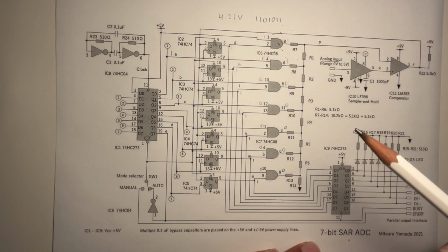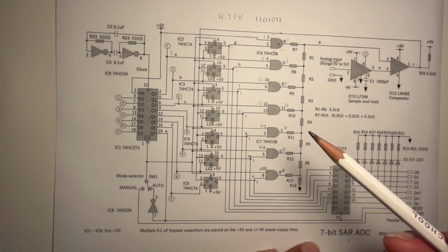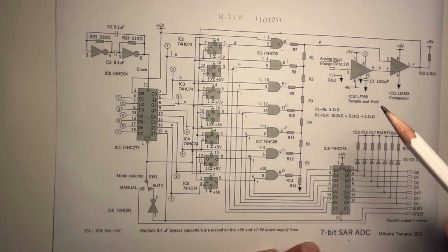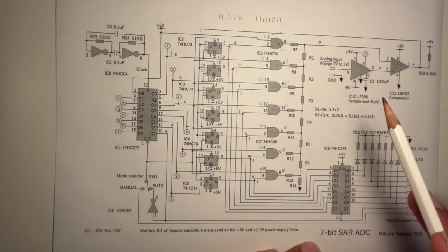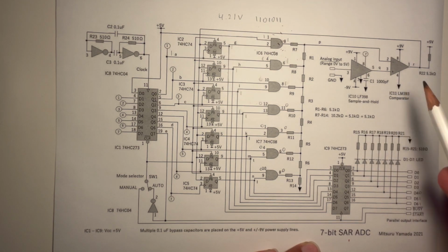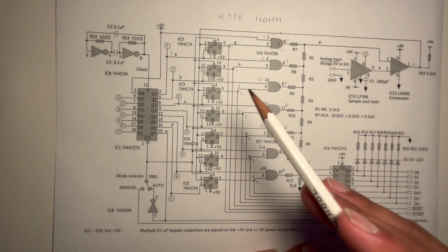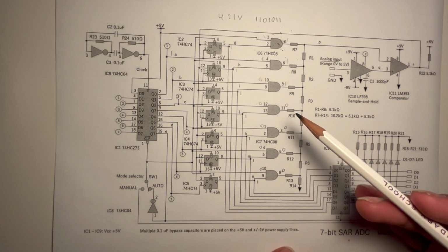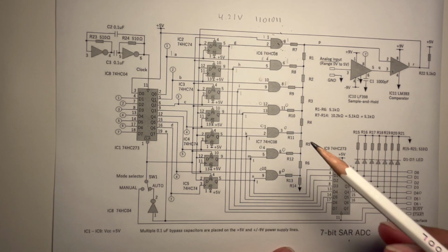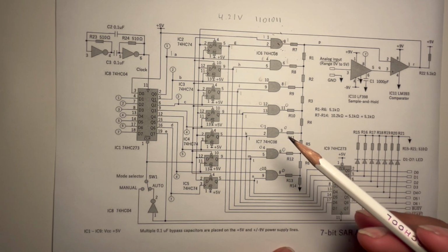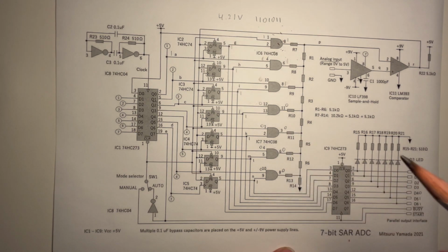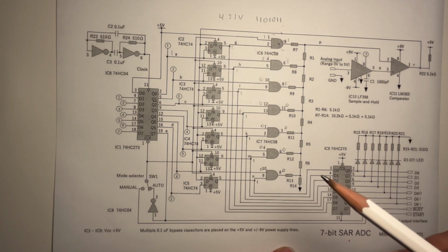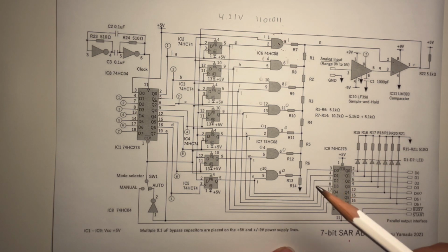So essentially the SAR ADC continuously guesses that the voltage is above a certain threshold, then checks if it's above that threshold using a comparator, and then updates the data bank accordingly and continues on the next iteration. This guarantees that every single measurement using a SAR ADC will take the same number of clock cycles, which allows it to be used in precision and timing sensitive applications.